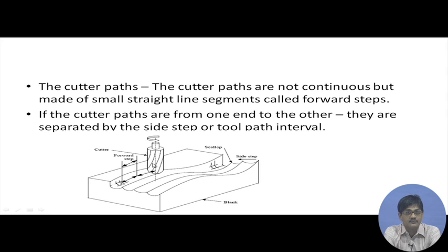they are tolerated through form tolerance. Here the side steps are creating surface roughness, and we will have a tolerable value of these upraised portions, so that all of them will either have to remain within a tolerance value, or preferably all of them should be of equal height everywhere, which is much more difficult to attain.